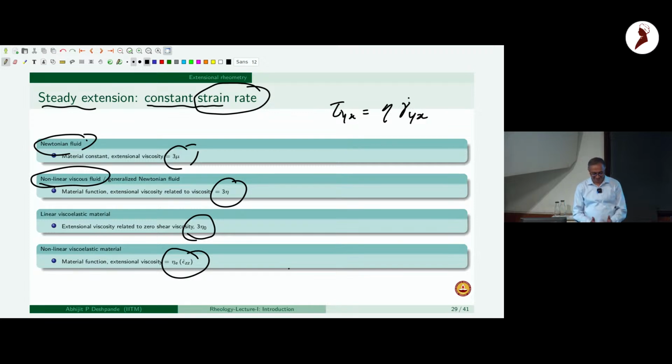Yeah. So as I mentioned, if I have to make good fibers reliably, see, let's say the final diameter of the fiber is 5 micron, right? But I cannot extrude through a capillary which is that thin. So what I do is I extrude it out of a capillary which is, let's say, about 200 micron, and then the jet of the polymer I stretch. And that stretching is done basically through rollers. I take that strand on a roller and rotate the roller quite fast so that the strand gets stretched.